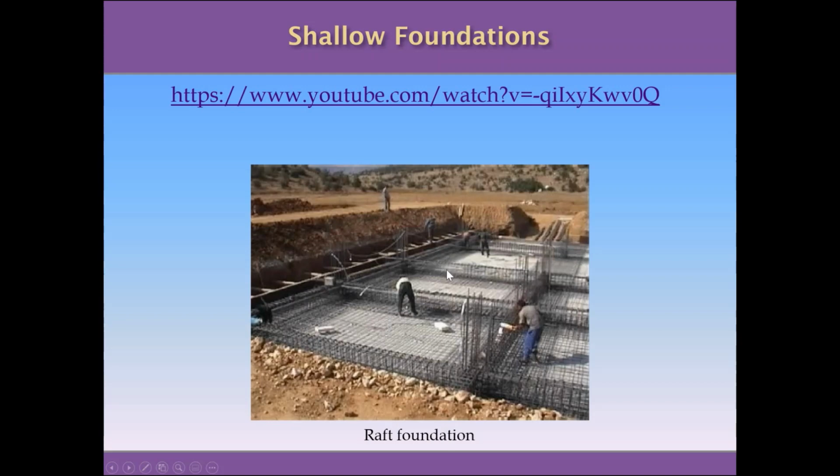So, of course, preferably, if we can use isolated foundations like pad foundations or strip foundations, it's going to be cheaper, but the raft is sometimes the only solution we find to spread the loads from the building in an effective way, for many reasons. For example, because the soil is not too strong, or because the loads from the building are too high. You have another link here to see more details about the raft foundations.